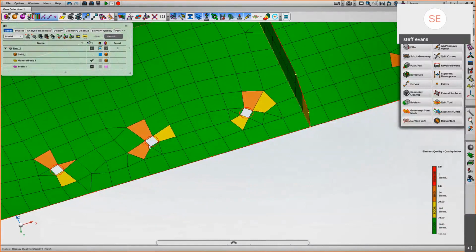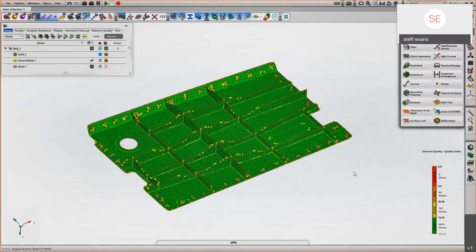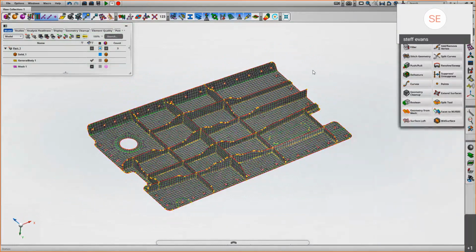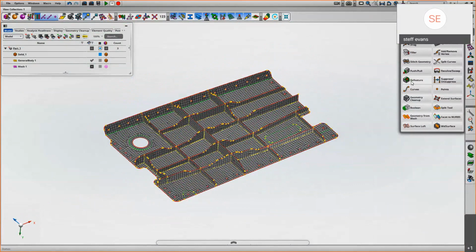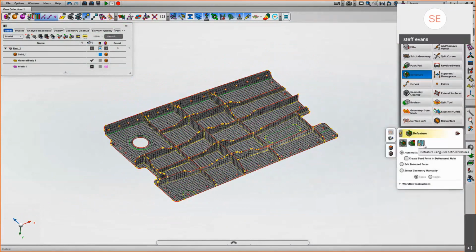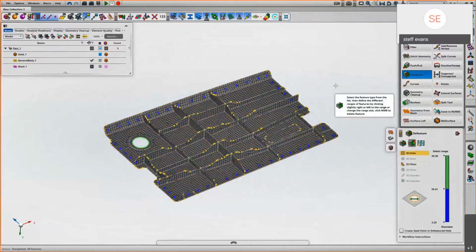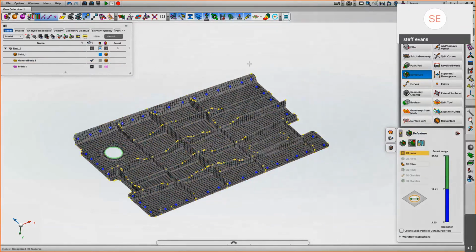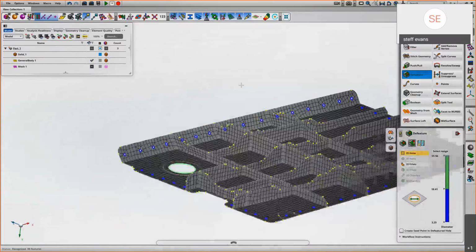You can see we've got a number of poor and bad elements around some of the hole features. So we've got pretty tight hole dimension given our 5 mil element edge length. So we're now going to use some of the defeaturing tools, I believe, to try and get rid of the holes and replace them with hard points. Okay, so we can defeature manually, but in Apex we've got this defeature by identified feature. So click the geometric entity, and we can do this for many entities in one hit, and then it will give us a map, if you like, of all the types of features it's found, I should say.